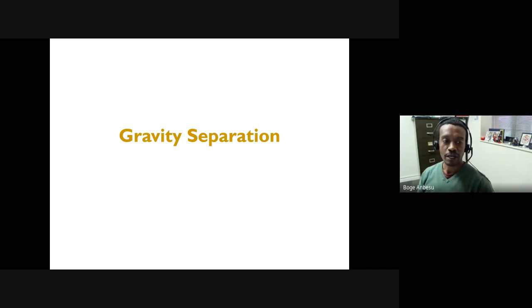But obviously, when you design equipment for a gravity separator, there are a lot of things happening. For example, you would have already started with a fine material that has been ground. So it's not like you're dealing with very large rocks, you're dealing with fine particles. And those fine particles are suspended in water or some kind of media as well. So the motion and the settling will be impacted by a number of factors. When people design a gravity separator, they will consider the motion of particles inside the separator and things like that, in addition to, of course, the mineralogy.